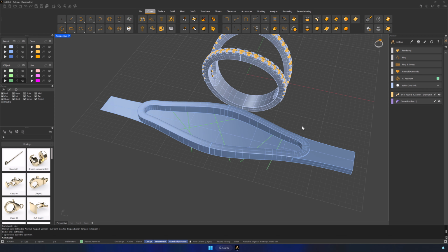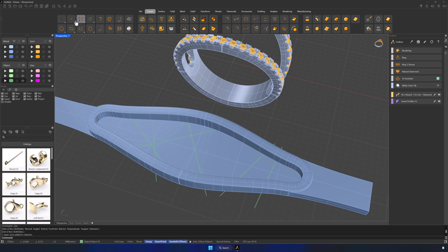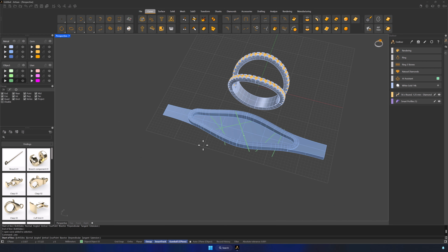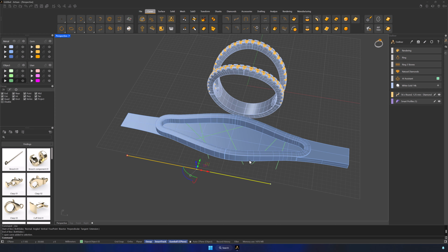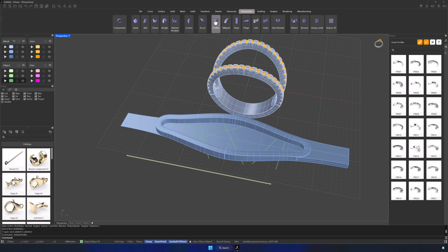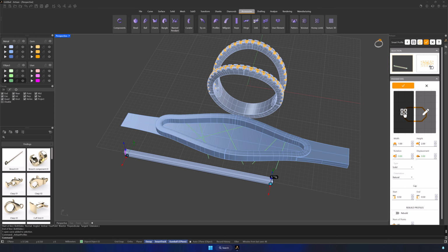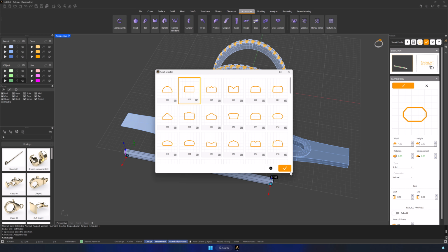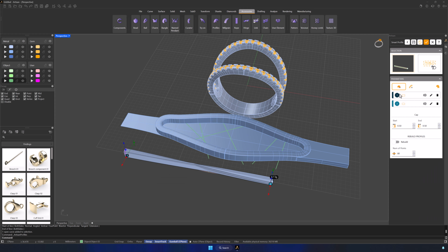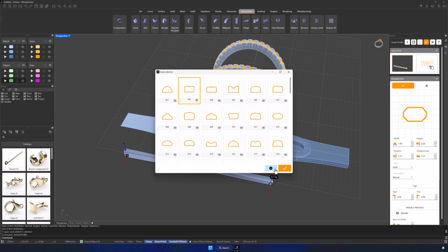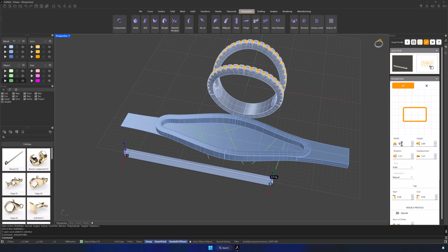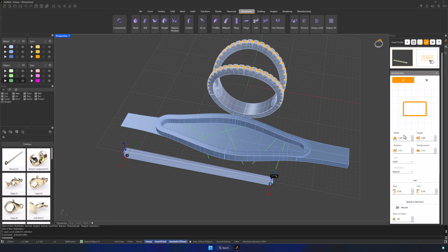Once the curves are done, we'll create a line to define the profile we'll use. Go to the Accessories tab and use the Profiles command. Again, we'll use the PRO08 preset, then click on Edit, and we'll adjust some parameters. Change the profile curves to 002, as we did before, for both profiles. Change the width of both profiles to 1.5mm, and once you're done, accept the command.